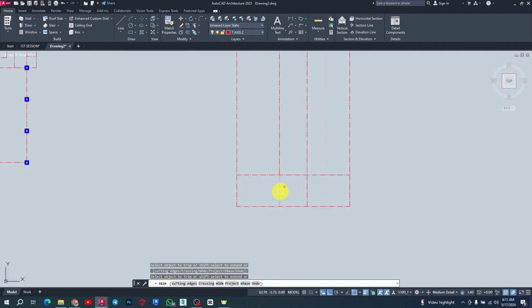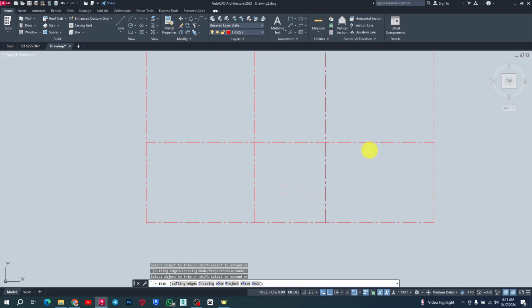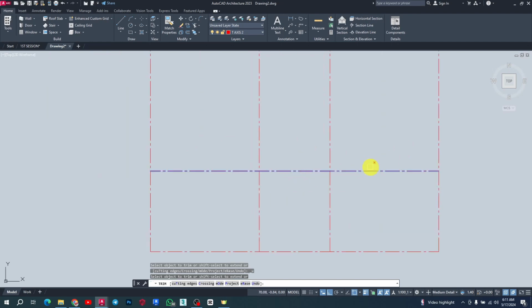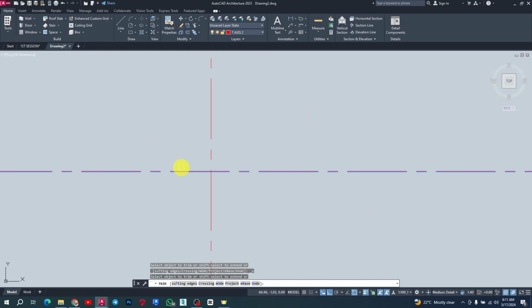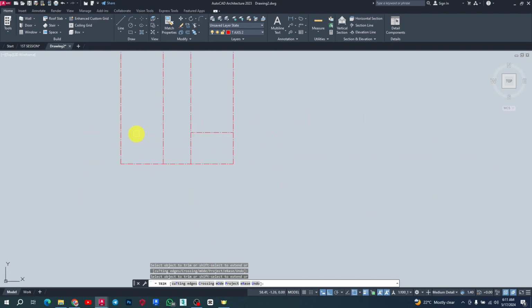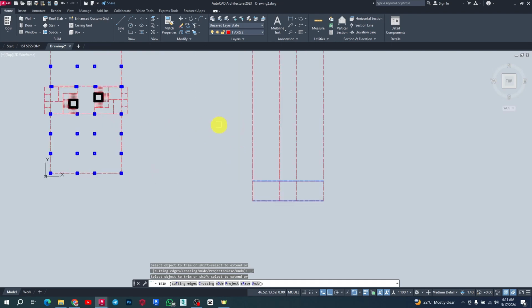And there's a secret, some tips that I don't want to give you right away when you want to trim. If I want to remove this line completely, I want to be left only with this one. I will not want to go and click and then be left with this one. So if I want to be left with just this segment here, what I will do is zoom until I'm not seeing the other parts behind. So I'll click and delete. When it's out of your view, from the view environment, that one will disappear. Okay, so let me take that back again.